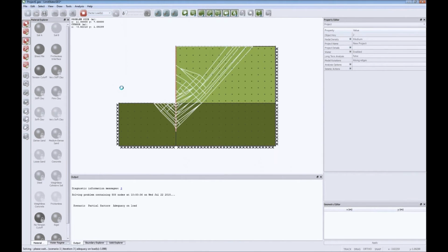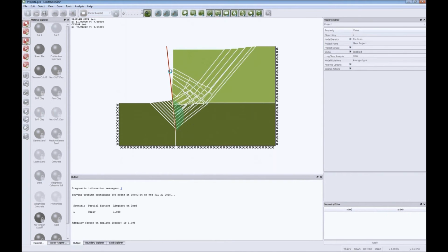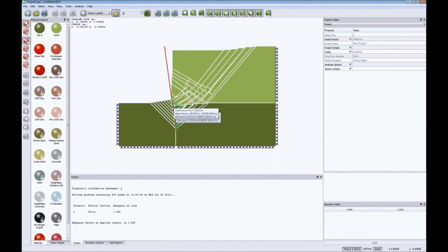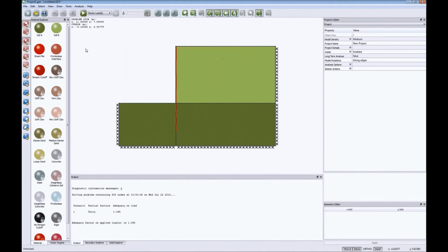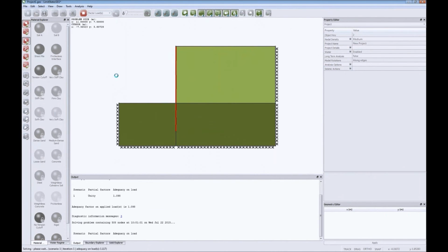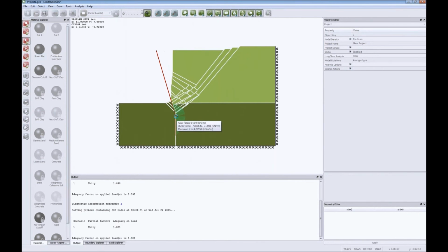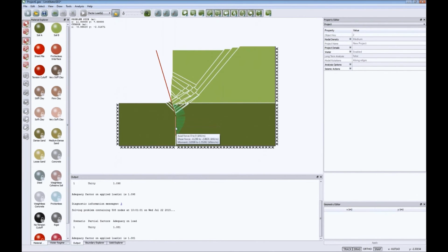If I click solve here, it's set up a particular default geometry and soil type. It's able to model a tension crack here, and what we have displaying down here on the element is now the moments on the wall. But just to show that we can model bending, if I set this to a very low value like 5, then what we should find is that the mechanism of failure moves up, and that the wall itself then suffers bending collapse at this point here and stays rigid down here. So it is possible to model those aspects.